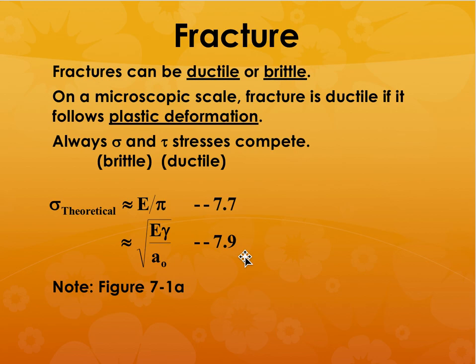Or even in the case of a thermoplastic material, if you are pulling it apart, it elongates quite a bit. So if there is a lot of elongation, that means there is plastic deformation that has taken place. Okay, so that is a ductile failure. The other type of failure is a brittle failure.